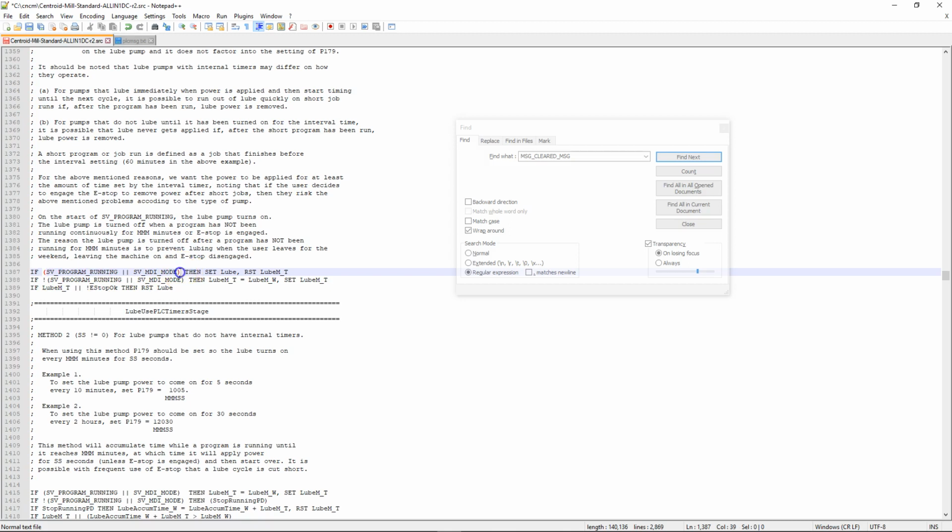But when you're customizing your PLC program, by all means, if there's two parts to the condition that need to be met, I always say put them in parentheses. Because right now you can see that the next line is the inverse of either of those.